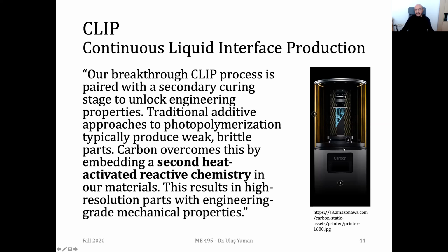In the next slide I will show, they have an oxygen permeable window, and by adjusting the amount of oxygen in the process, they can have a kind of continuous interface. Although they claim that it's totally continuous, since it's a layer-based method, we cannot obtain whole continuity. The thing is that the thickness of their layers is very low, around 10 micrometers, I guess. So that's why they prefer to use the term continuous liquid interface production.